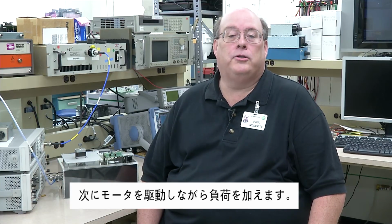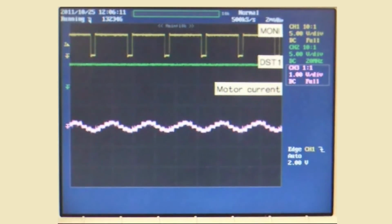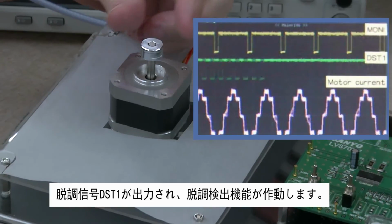Next, we touch the motor to add load to the motor while it's running. When a load is added, the power consumption increases, and then the device optimizes the current level. Next, we add more load to the motor. The motor eventually becomes out of sync or stepped out. The stepped out detection function is triggered, by which the DST1 signal is sent.